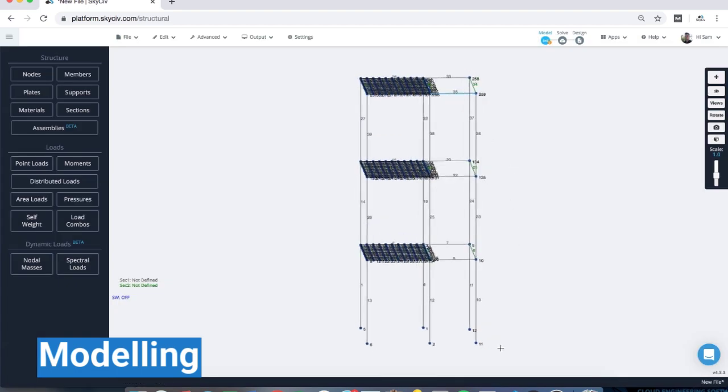And just on that note as well, with selection and graphical controls, I can hold control and select, and if I go one way, so if I go to the right, anything in contact with the box will highlight. So I can see members 33 and 35 are being highlighted there. Alternatively, I can go the opposite direction, and that will just highlight any elements that are strictly within the bounding box of my selection tool.